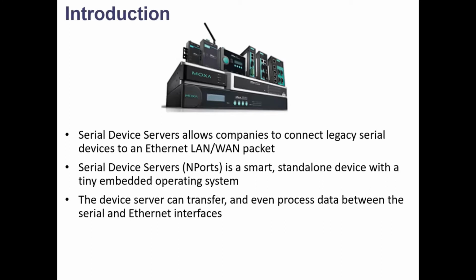Several asynchronous serial interfaces, including RS-232, RS-422, RS-485, CAN bus, Profibus, and others, are currently in use to connect various types of devices, such as sensors, card readers, meters, and PLCs. We concentrate on products and applications that require access to RS-232, RS-422, and RS-485 interface devices via an Ethernet connection. Since these three serial interfaces are the most widely used in industry, the transformation between the serial and Ethernet interface takes place at the electronic signal and network protocol level, such as transformation of data from the serial RS-232 format into a format suitable for the TCP/IP network.